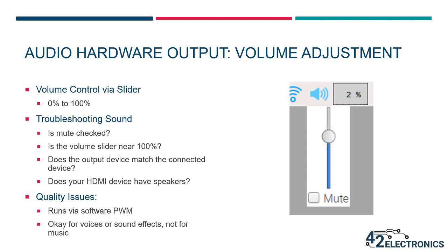Also, don't assume that all HDMI devices have speakers. HDMI connected TVs will have internal speakers, but most HDMI computer monitors don't have internal speakers. So when in doubt, check the specifications of the device to determine its audio capabilities and required connections.